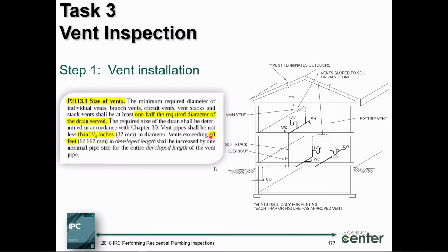When you have vents that exceed 40 feet, ladies and gentlemen, in developed length is where you measure the horizontal pipe, the vertical pipe, and around the fittings. It's the full measurement of all the vent pipe, including the fittings. All right. So that's first and foremost.